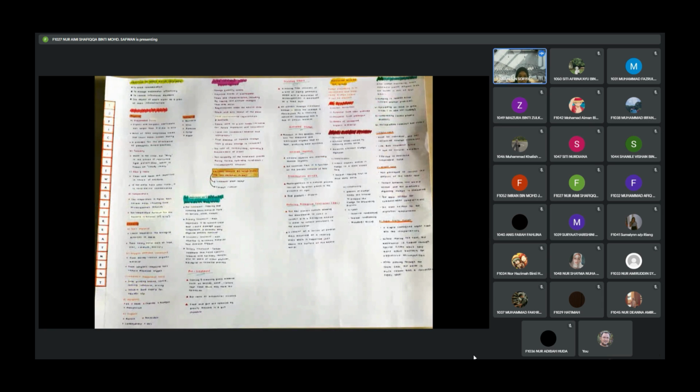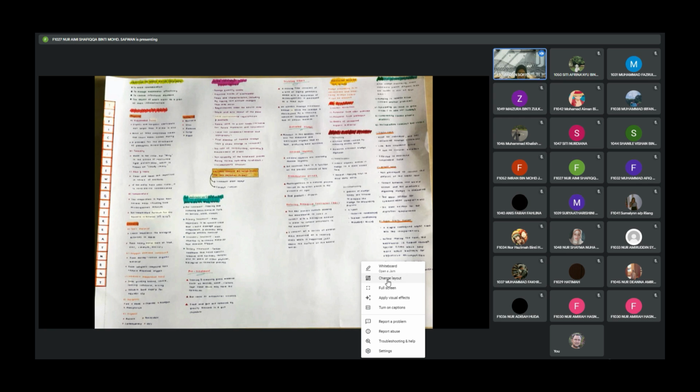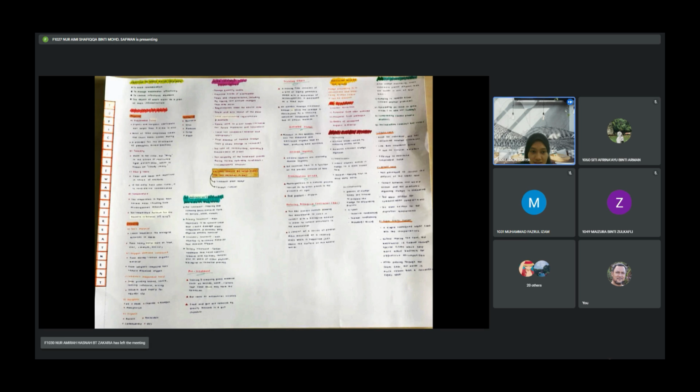The last chapter is about sewage treatment. The objective is to avoid contamination, manage wastewater effectively, and to control infection disease. Next is characteristic of sewage. There are 4 physical characteristics, which are suspended solids, turbidity, odor and taste, and temperature. For chemical, there are 5 characteristics, which are toxic material, oxygen demand compound, insoluble suspended solid, inorganic, and organic. Last one is biological. Biological also contain 5 characteristics, which are bacteria, virus, protozoa, fungi, and algae.